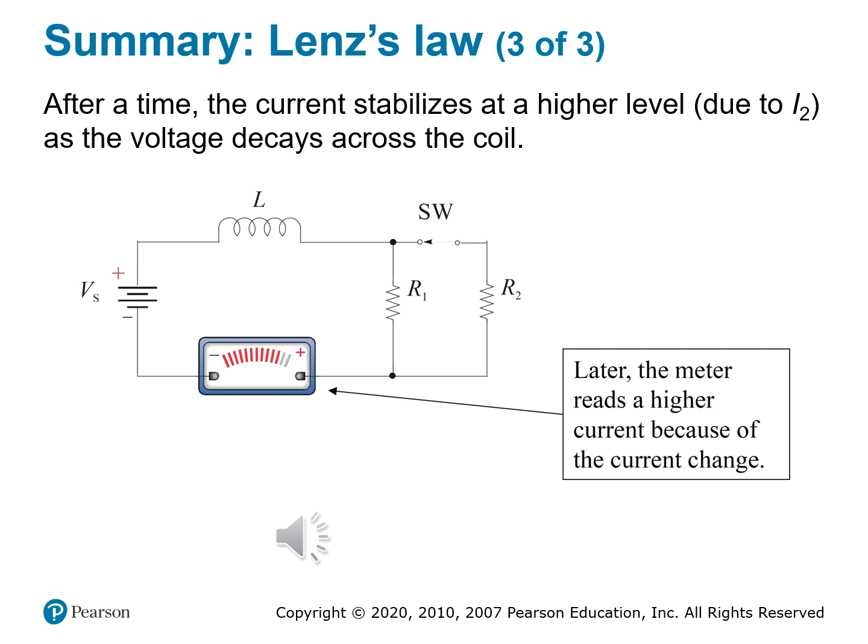This offers a lower resistance path, and this perfectly illustrates transient behavior in inductors: the initial opposition to current change, exponential voltage decay, and final equilibrium, where the inductor's only role is resistance, if any. Understanding this is useful and it helps explain relay delays, inrush currents, and why you can hear a click or snap when switching inductive loads.